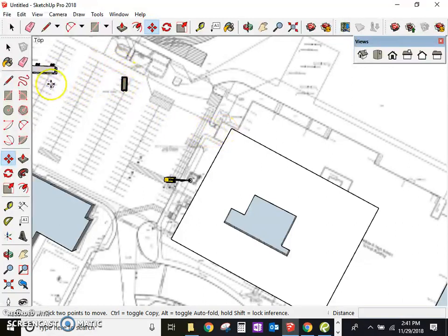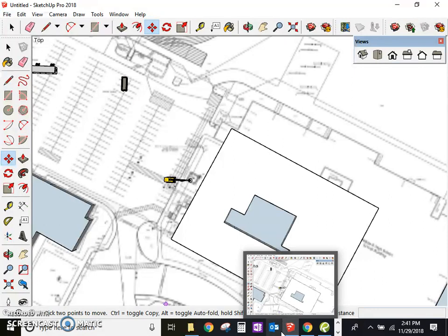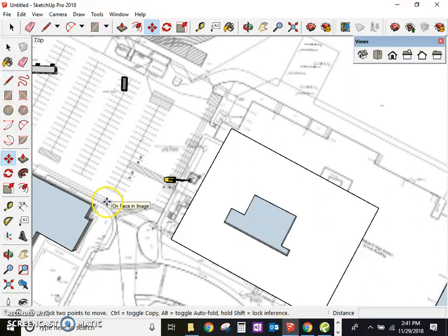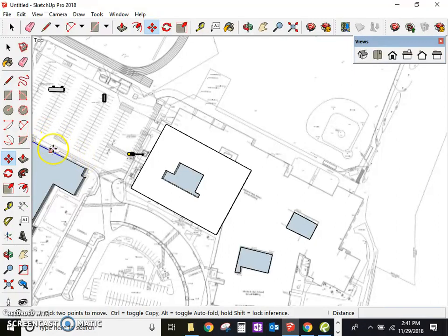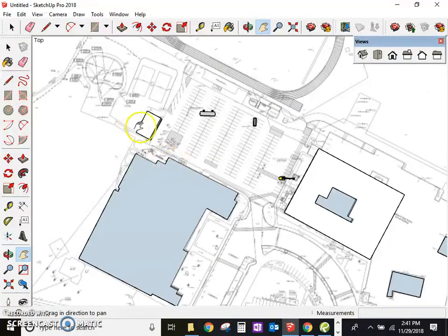Your trailer you're going to want out of the way. Your dumpsters somewhere where you can get a truck in and out. You can even show the roll-off dumpster truck if you so please, and then a fenced-in material laydown area. Also, make sure, again, you're not blocking any of the access to the buildings and grounds here, all these manholes, and the loading dock for the elementary school.